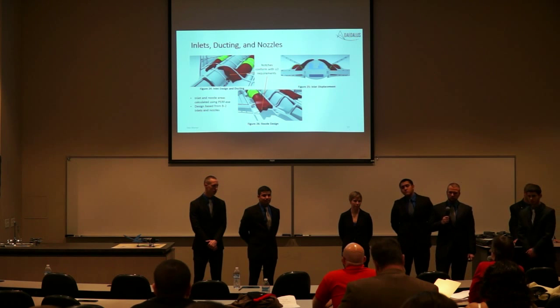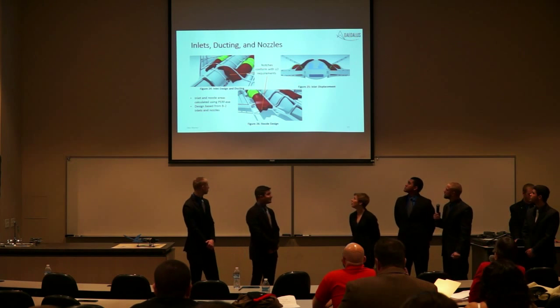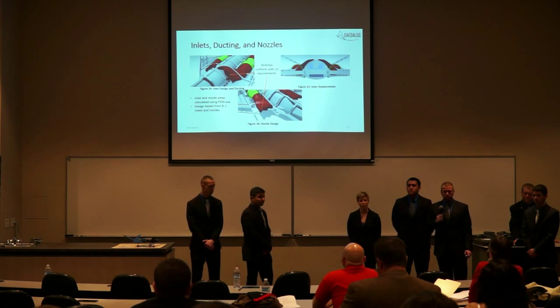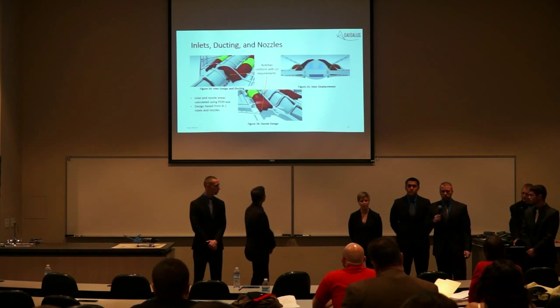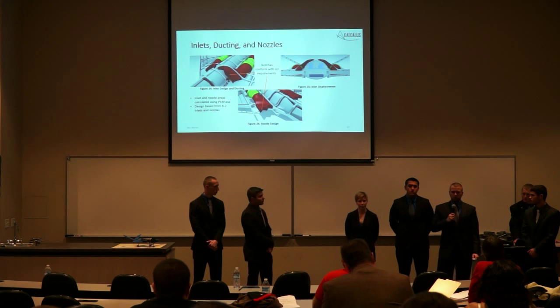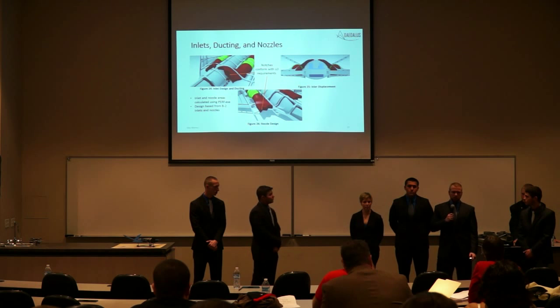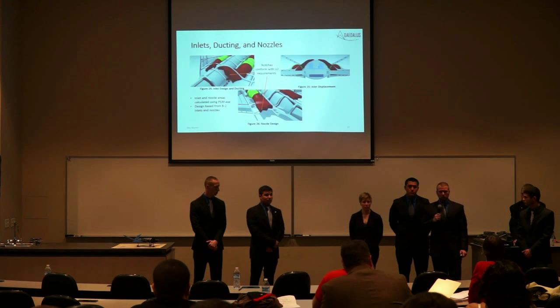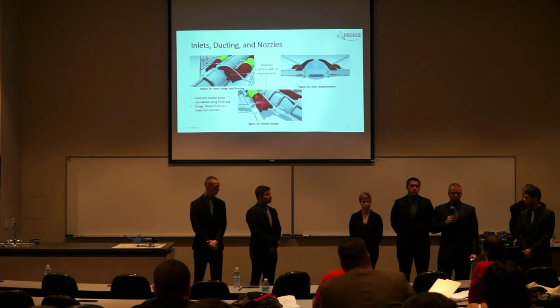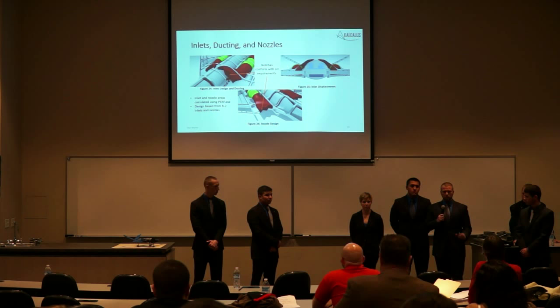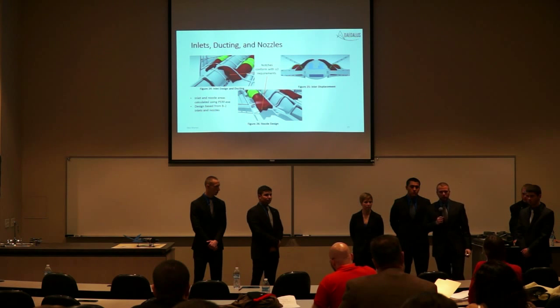Okay. Your exit. Now the area of that exit, what was that based on? So that came directly from perf. We were able to model the engine with its mass flows and all the parameters of the engine, and one of the outputs that perf has is the areas of the nozzle, station 18.